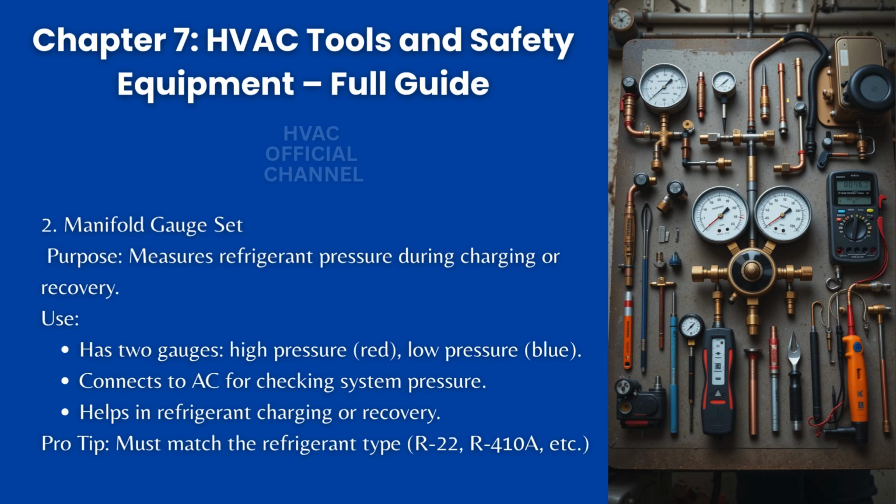2. Manifold gauge set. Purpose: measures refrigerant pressure during charging or recovery. Use: has 2 gauges. High pressure, red. Low pressure, blue. Connects to AC for checking system pressure. Helps in refrigerant charging or recovery. Pro tip: must match the refrigerant type: R22, R410A, etc.